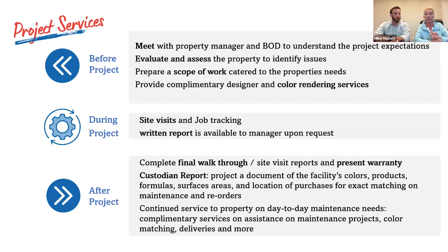And that's where we do our mill tests. We provide all of the reports for that for you and make sure that they're getting the products. Oh, and we will also check their receipts. We've done that before to make sure that they're buying the proper amount of paint that we feel, as we see the project moving on, to make sure they're buying everything that has been promised to you. Yeah, if it's 100 gallons of top coat that ends up being purchased and 8 gallons of primer, that's going to raise a big red flag for us.